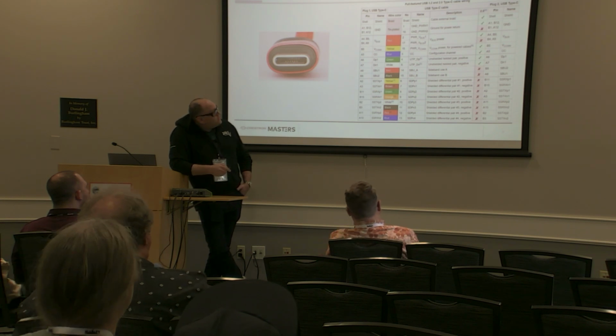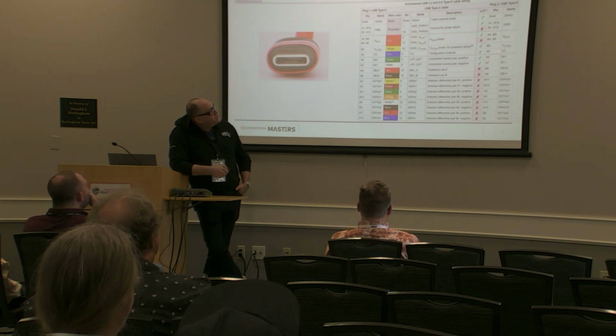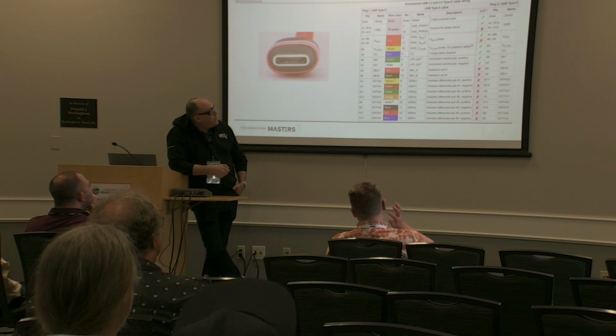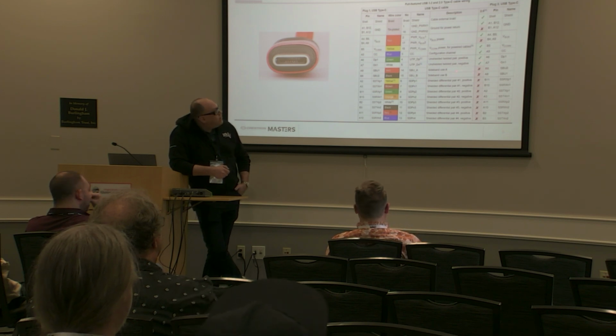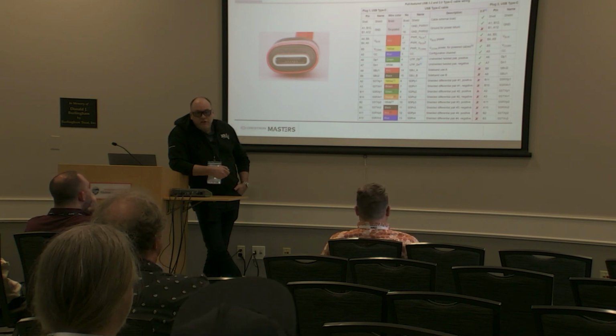So you can see in this chart here, we've got these check marks. They're basically saying these pins are associated with our USB 2.0 pins, right? So here again, just like we talked about before, here's our unshielded twisted pair. That is our original USB 2.0 pair, and it's still there in USB-C. Now, there's the differential pair 1 and 2. That's the one from USB 3, right? So it's there in your USB-C as well.